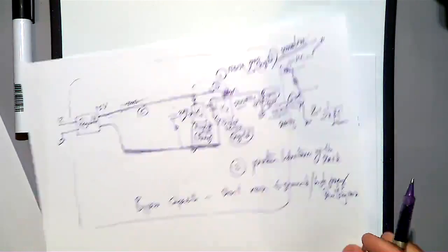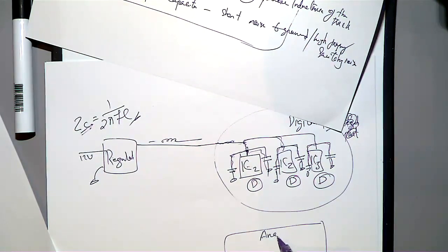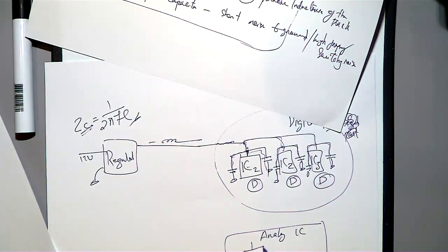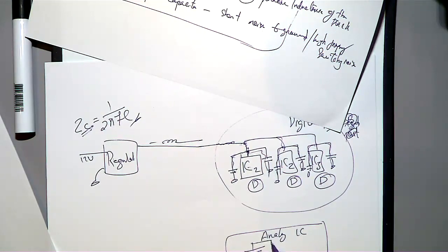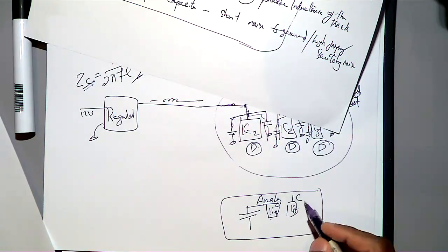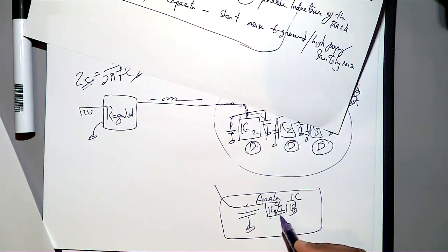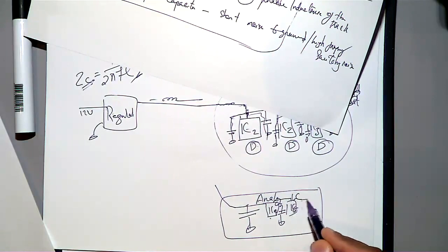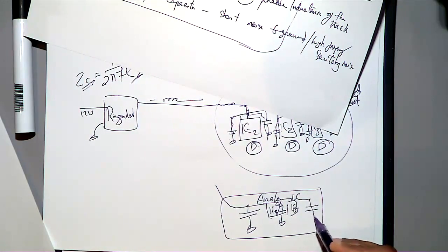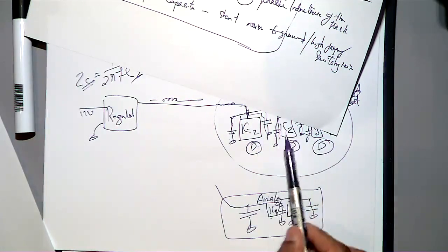So we are isolating. Then what we will do is put our analog ICs here. All the analog ICs will also have bypass capacitors, IC4, IC6, sorry. So these are analog ICs, this is the analog part. Analog is grounded, so again the analog has capacitors. So the analog part is isolated: analog here, digital here.